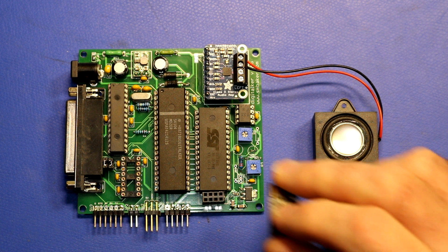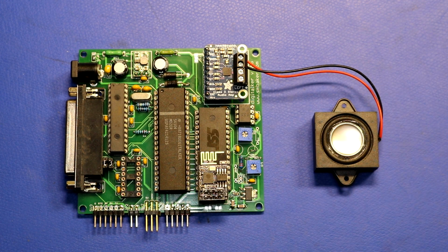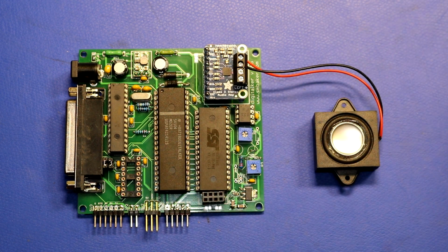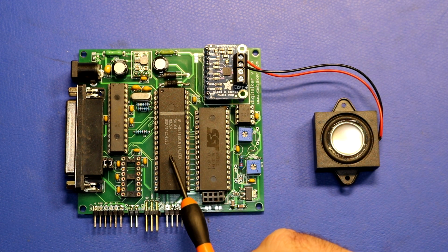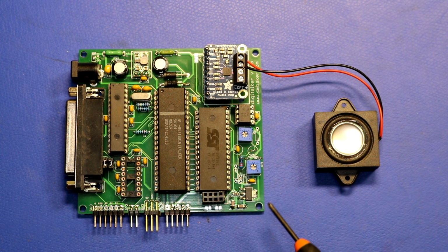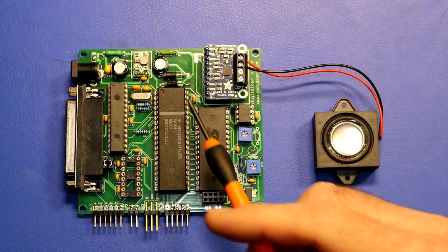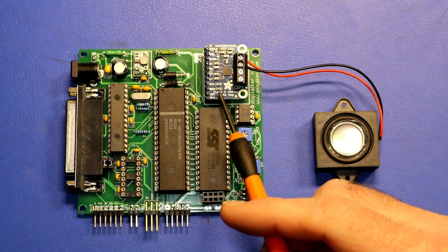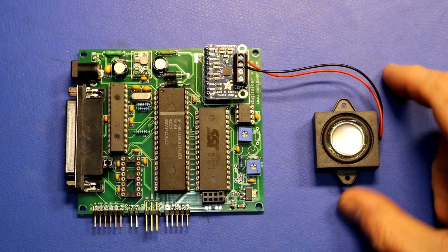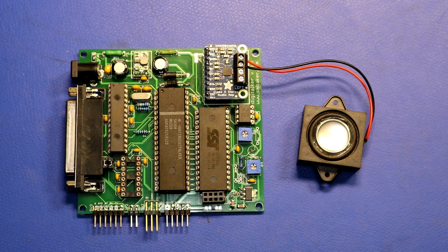If you want to use the ESP8266, you would plug in right there. We have the Digitalker ICs. Here's the big Digitalker IC. Here's the 39SF040 external ROM. Speech comes out, goes into the op-amp, and into the Adafruit TPA2016 amplifier. And then I have it going into this rather small speaker. So as you can see, pretty straightforward board.